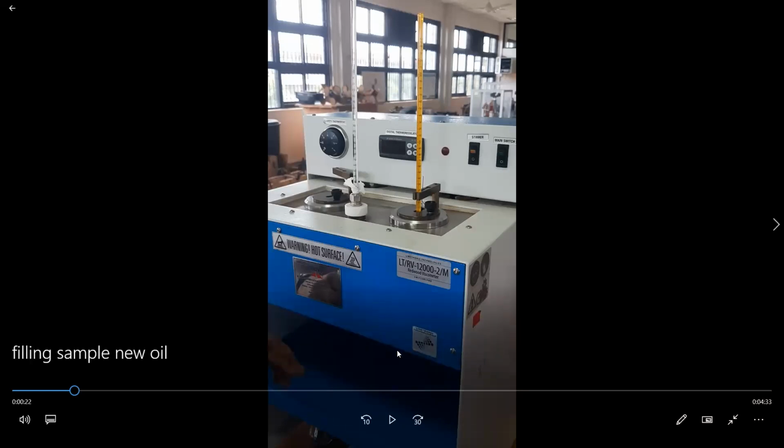Then again we have to put that sample into this cylinder, then heat up to 70 degrees Celsius. After reaching 70 degrees Celsius, we again collect the sample, and while collecting, we measure the time taken to collect a 50 milliliter sample. Using that time, we can measure the viscosity at 70 degrees Celsius. Like that, again we put it in and heat up to 80 degrees Celsius. Like that, at every different temperature, if we know the time to collect 50 milliliters, we can measure the viscosity.